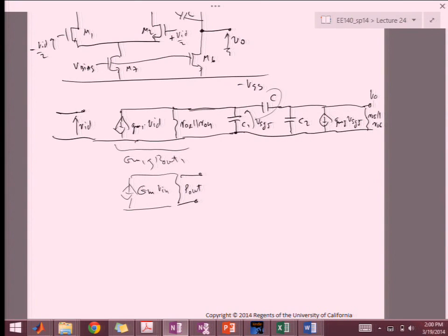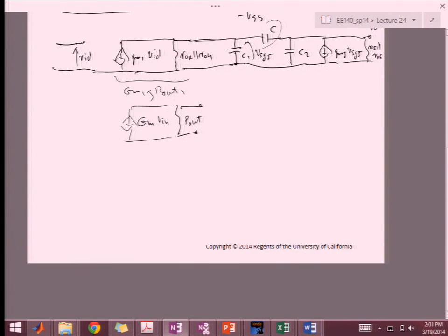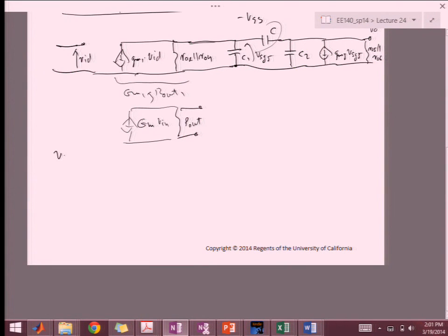So if you look back at what we did when we analyzed two-stage amplifiers and the impact of this, regardless of whether it was CMOS or not, we had exactly this same situation where we had three caps like this, and R from the previous stage and R from the second stage. So if you looked at the transfer characteristics, it looked something like this.